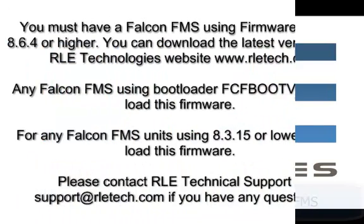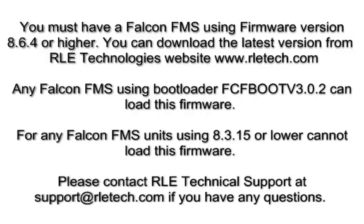To get started, you must have a Falcon FMS using firmware version 8.6.4 or higher. You can download the latest version from RLE Technologies website at rletech.com. Any Falcon FMS using bootloader FCF boot v3.0.2 can load this firmware. Any Falcon FMS units using 8.3.15 or lower cannot load this firmware. Please contact RLE Technical Support at support@rletech.com if you have any questions.